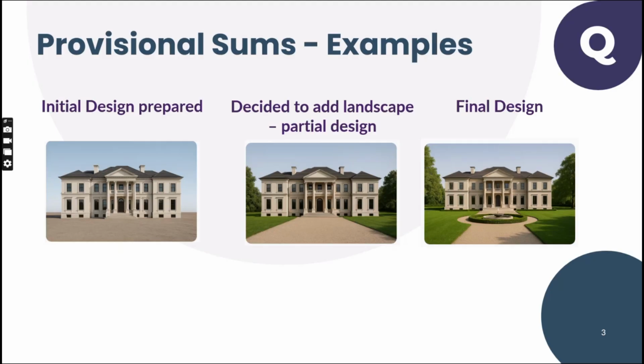So there's a question from Happy Sharma. In an item rate contract, is provisional sum added as a BOQ item? Happy Sharma, normally there will be a separate bill of quantity for the provisional sum item, because you will not be adding or considering that amount into your contract amount or price.